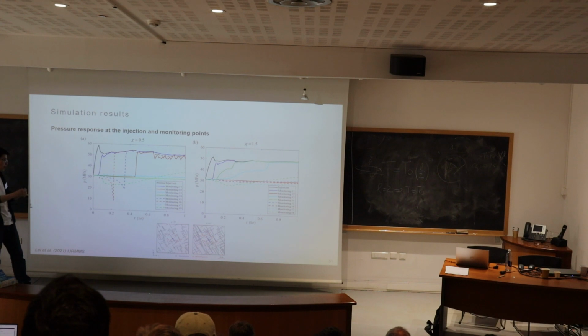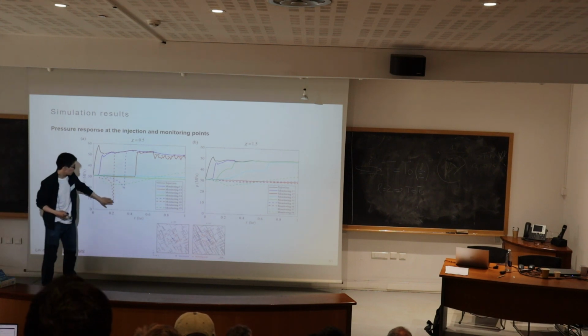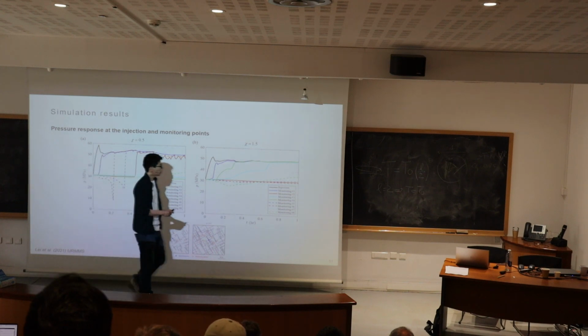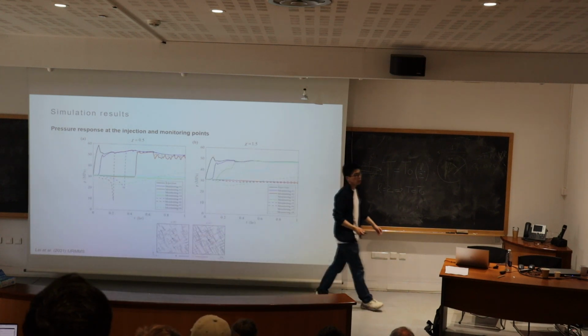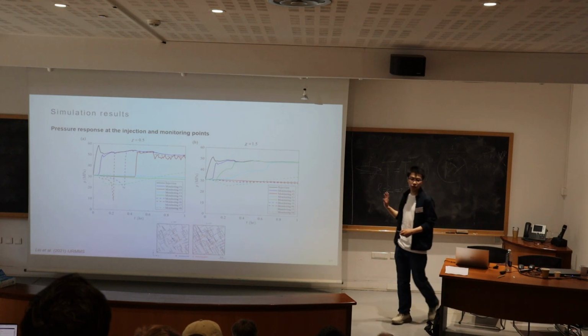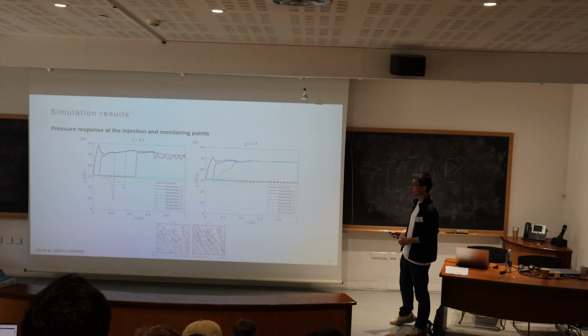So before they arrive, the tension stress builds up and reduces the pressure. And as soon as the new cracks arrive, the pressure quickly builds up. So this indicates the importance of considering the hydromechanical coupling in order to understand the responses of the fractured rock.